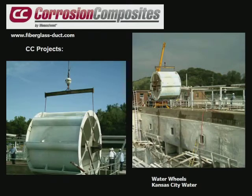The paddles used to be driven with chains and motors, and that's pretty common in a lot of the plants. What we did here, the city had devised a wooden water wheel, and they blow air into the buckets that you see, and as the air makes the bucket rise, it generates torque, and they can spin 16 of these mixing paddles with one air wheel. So the plant now has, I think, 38 of these wheels. They're 13-foot diameter, and they operate with 2 air pumps.